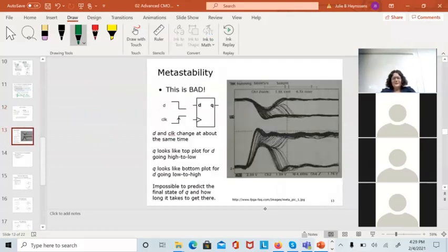Okay, this is really bad. And I've seen stuff like this, like when people were testing stuff like this at Micron when we were there. Let's set this up to make it purposely bad. What's going on here is you've got this clock edge, and exactly at the clock edge, and this is one thing that Becky was talking about in 310, you decide to change your D input at the same moment as the clock edge happens.